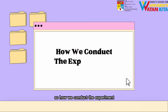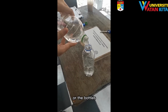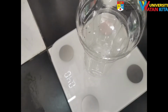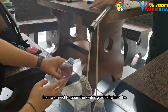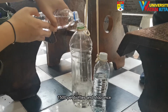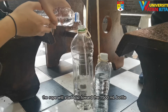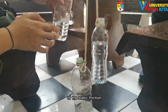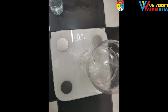So how do we conduct the experiment? Firstly, we pour some water into both of the bottles. The water volume should be the same. Next, we hang the bottles on the fixed drum. Then, we pour water gradually into the 1500 ml PET bottle and stop once the rope starts to slip toward the 1500 ml bottle. Last but not least, we calculate the coefficient of static friction by using the difference of the volume of water in both bottles.